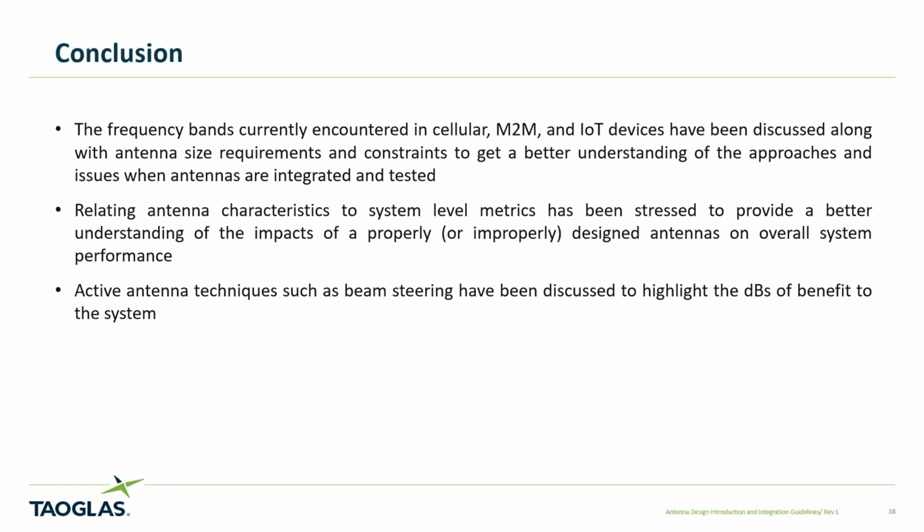On the client side, you cannot go with a single antenna. They need to form some type of array to get the antenna gain up. What I see in smartphones right now is a linear 4-element array. They'll drop, say, 3 of them in to provide somewhat robust coverage around that smartphone. Because you don't know the orientation of the smartphone, and it is mobile, and its position is always changing, you always have to anticipate the need to form a connection at different aspect angles.